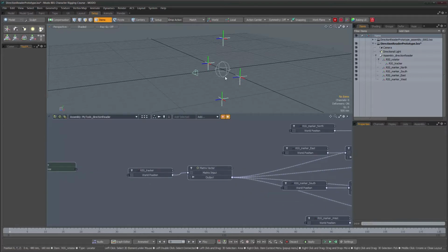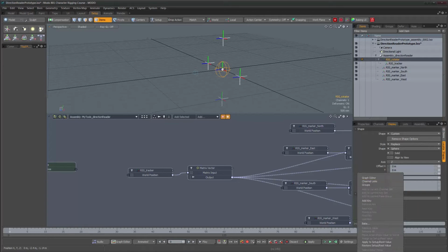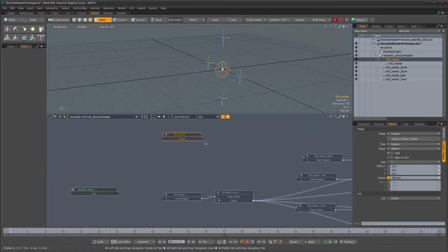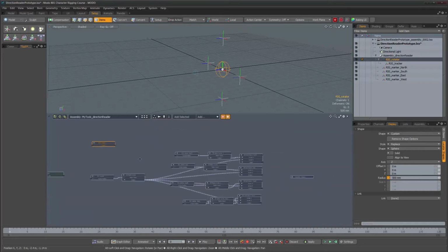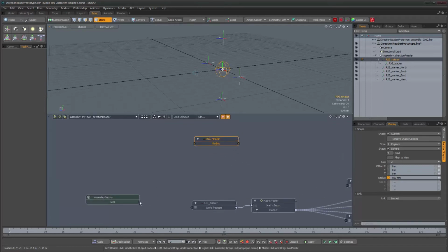That's the whole purpose of using assemblies, basically. So let's, for example, start driving this guy's display size, which is 500 millimeters. I'm going to select that channel, right click, and say add channel to schematic. You don't see it, it's off screen, but it's there. So immediately it brings the node in here, because it wasn't part of the schematic. And then we have our radius. If I wired this directly, let's see what happens to this value. It becomes 1 meter. So basically this is twice as big as I would actually like it.